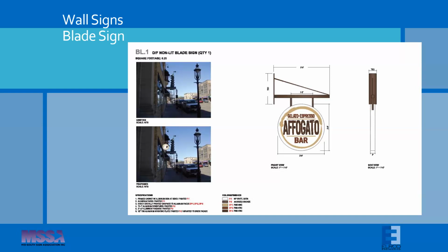Because this sign was designed as a fixed connection, the wind that's being applied to that sign face torques the entire bracket. If I remember right, this particular sign was being installed in an area in Florida that had very high wind speeds, and so the bracket just couldn't withstand the moment, that twisting motion that was being applied from that face. But the architect insisted that it have that look and feel rather than having chains so it could flop in the wind. And so the bracket itself had to be beefed up significantly in order to withstand those wind loads.